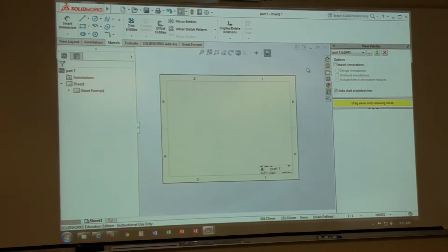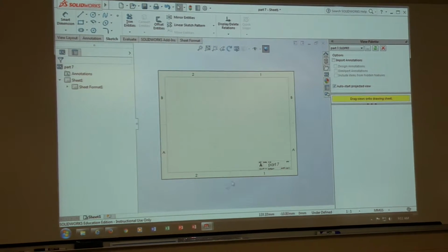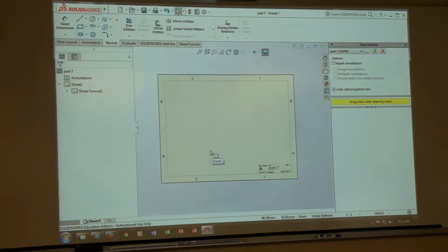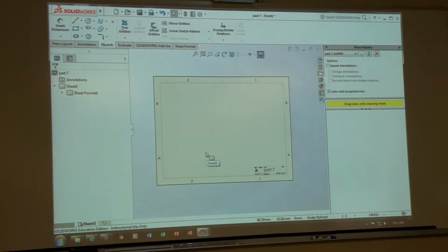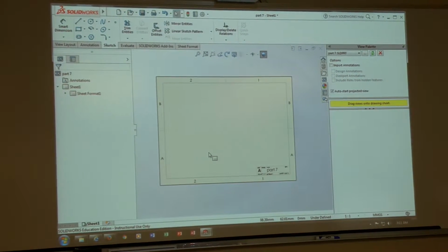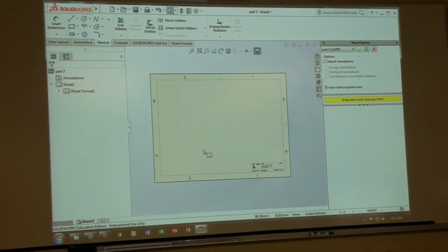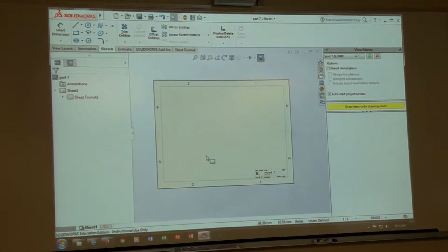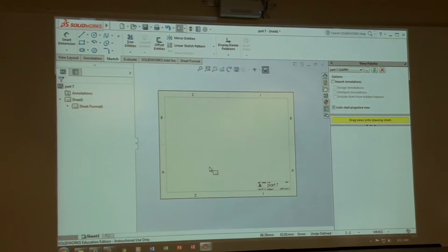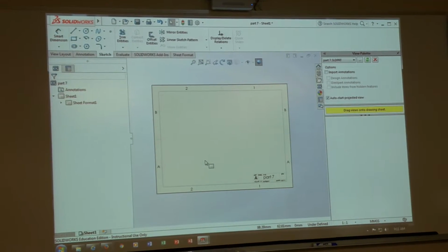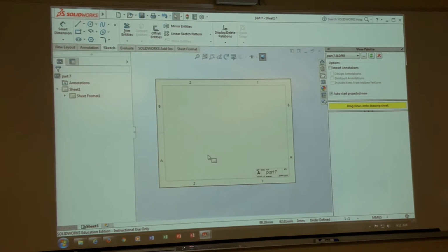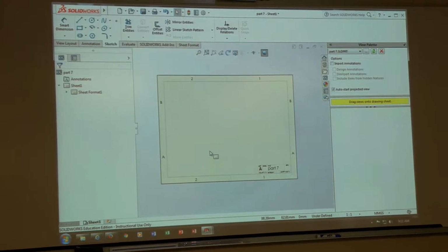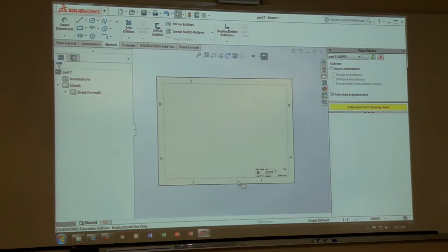We're not going to change the scale of our model to accommodate the border. You hear the way I said that? Your title block needs to be modified to accommodate the model you're bringing in, not the other way around. You don't go to half scale because your title block and border are too big. You actually lean out your title block. Okay? That's what we did.